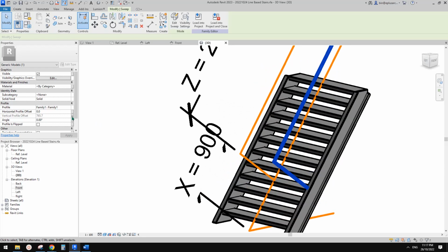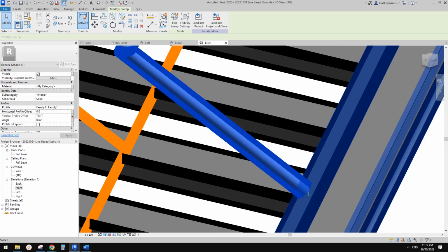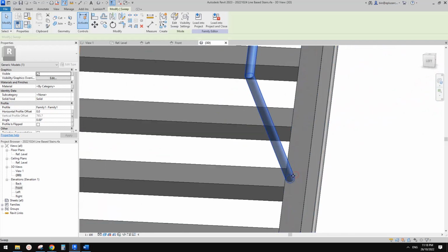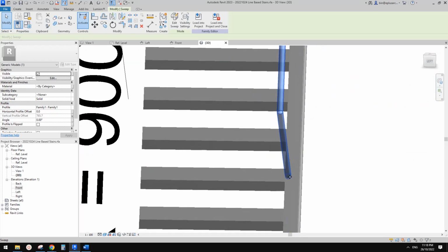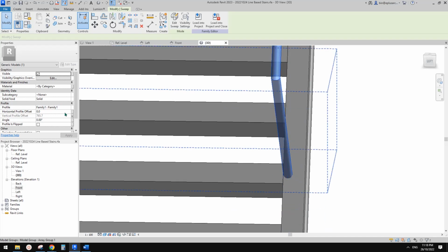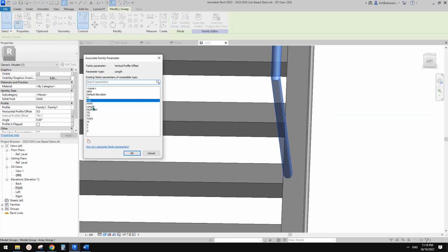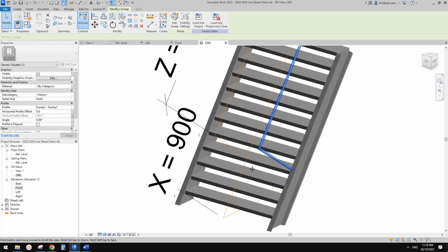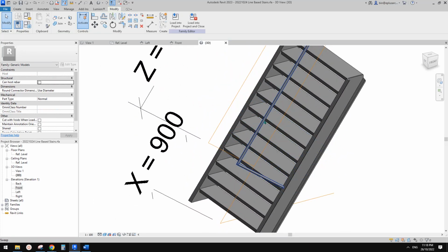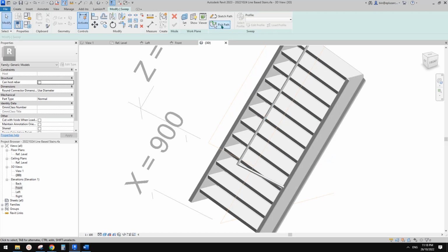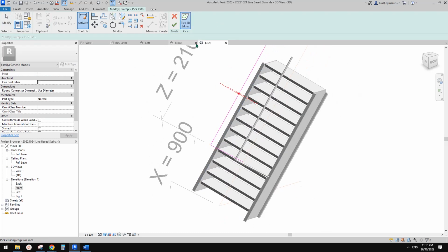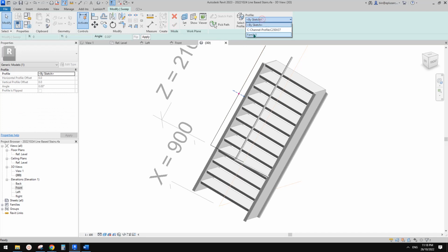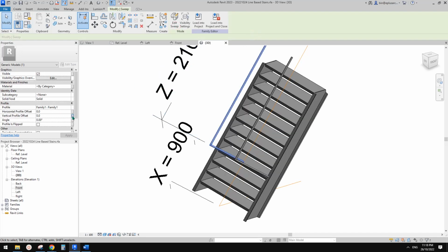And if we need to, you can adjust this a little bit. If you don't want this railing at this point, so you want to offset a little bit more, you just need to create another parameter to add a little bit more. But I think I'll just leave it for now. If we need another one, very simple, create similar, pick path 1 2 and finish, and just use the same, and this time just use the negative half width, it will offset to the other side.